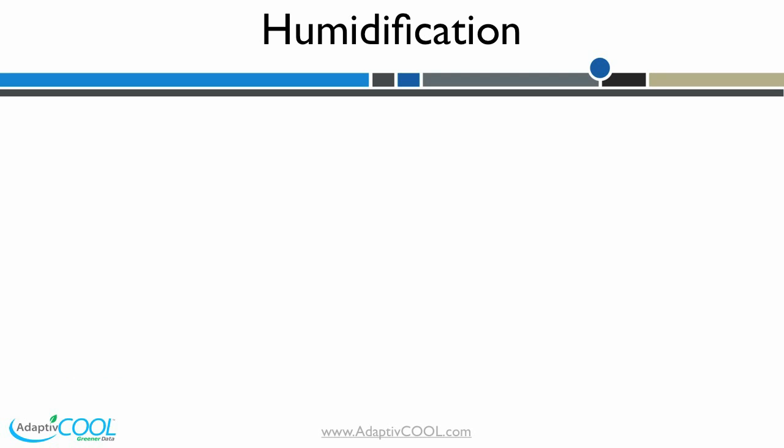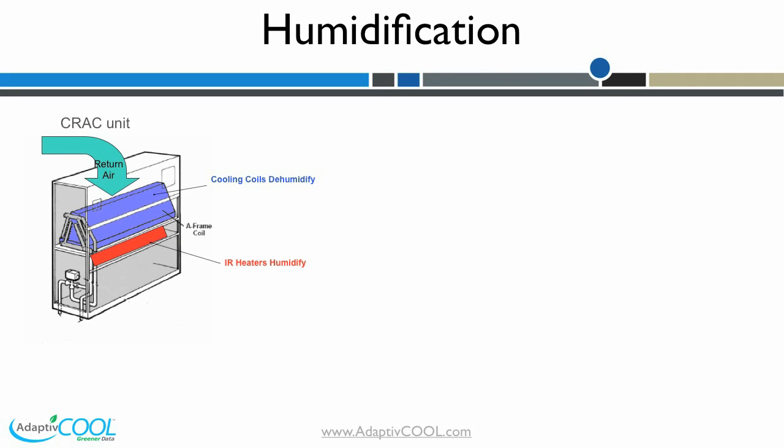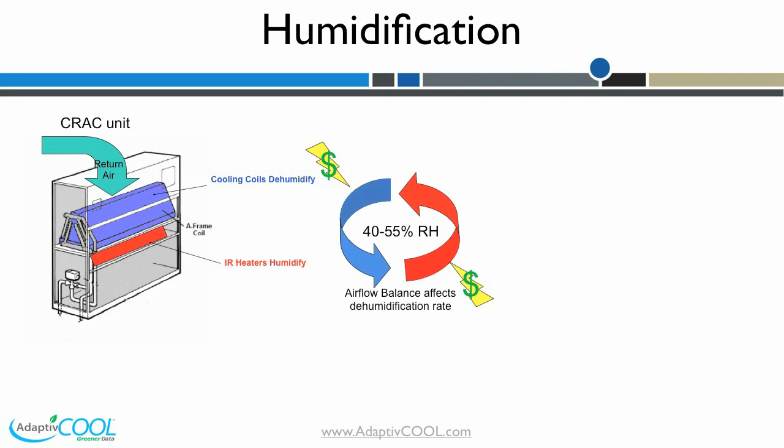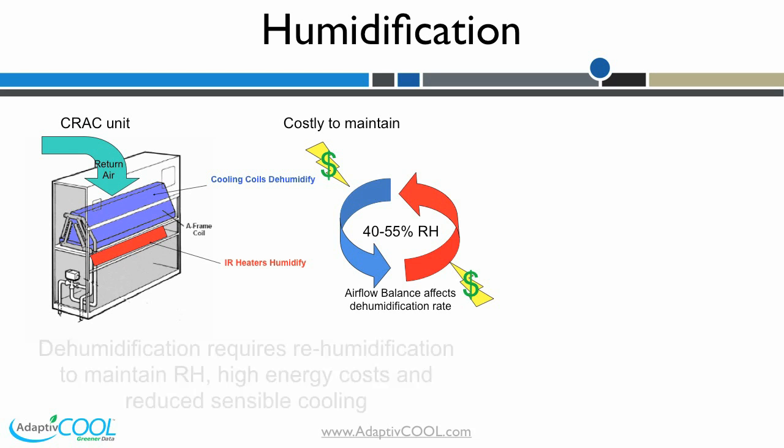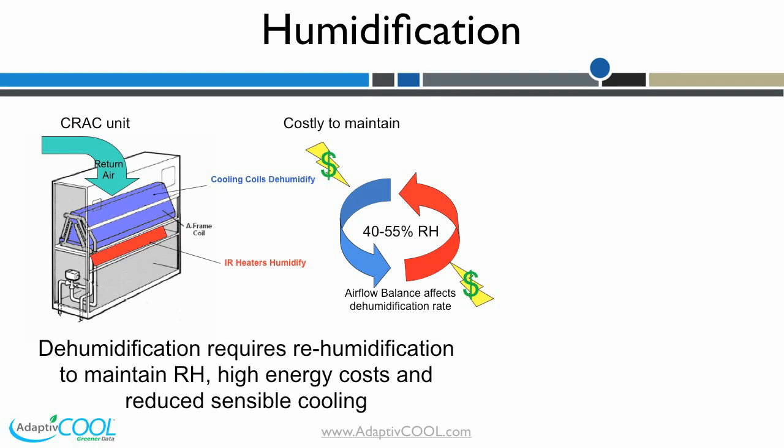Humidity in the warm air returning to a CRAC hits the chiller coils in the CRAC and immediately condenses. The cold air exhausting the CRAC is now low in humidity, so most CRACs are designed to humidify cold air. CRACs with different return air temperature can cause each CRAC to humidify at different levels, causing extreme inefficiency.